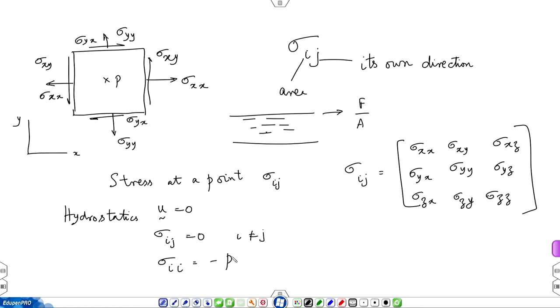So, when the fluid is in motion, we have to discover an equivalent system of equations, like the one in hydrostatics. How did we set up that equation? By reference to a natural law. What is that natural law? That's Newton's law of motion. Sum of all external forces equal to 0. That natural law, applied to a portion of the fluid medium, gave us the equation minus dP dz equal to rho g. So, the starting point is the natural law.